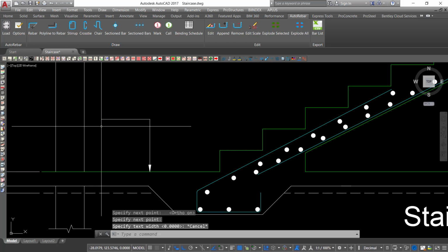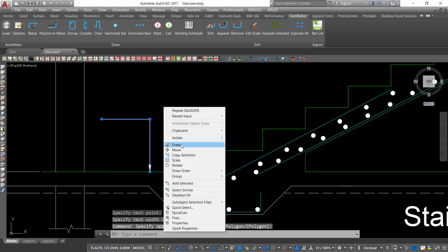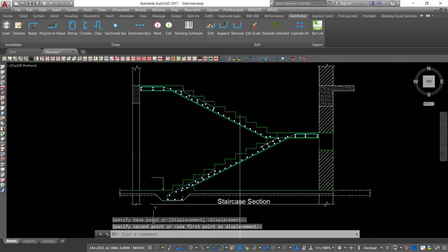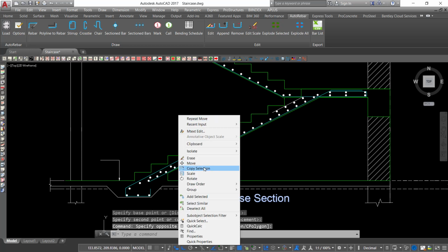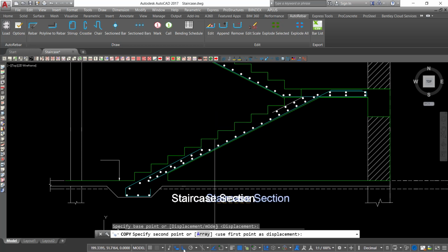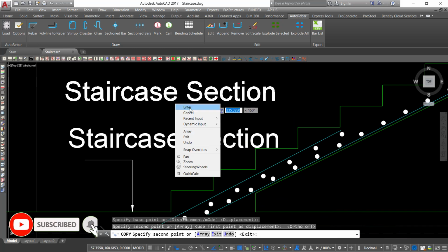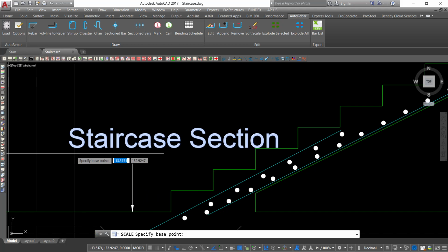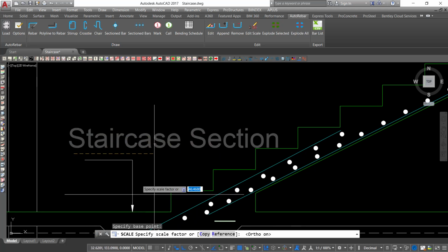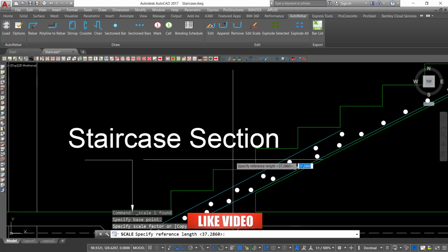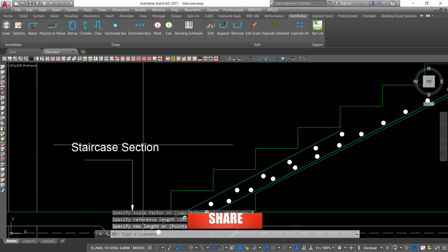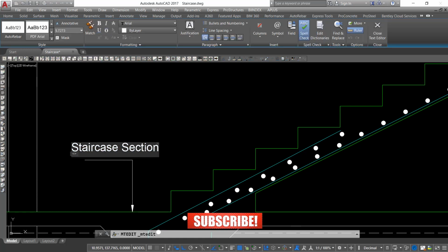We'll begin with that, and just enable auto mode, pick on that and type escape right there. I'm going to select on that and select move, and I want to start describing this. I'll pick that text, copy it somewhere here, double click or select it, right click, come to scale, and scale this down, because you don't want that big text. I'll double click on the text here and start feeding my own descriptions.